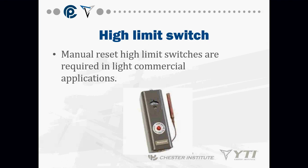So this switch here, the Aquastat, is high and low operating temperature switching, and this one is safety switching. If it gets to that point, it just shuts it down. Correct. The Aquastat is what's going to control the boiler temperature.